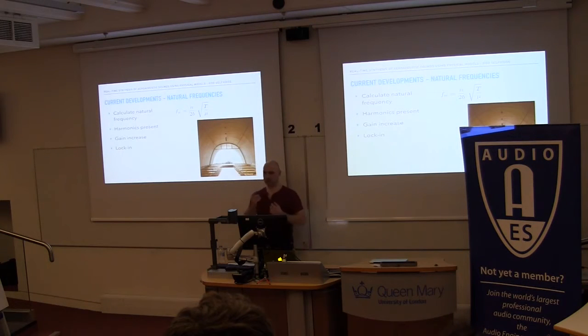And what also happens is the wind speed might go up a bit, but the mechanical process says, no, you're still going to shed at my speed. So it creates a kind of lock-in, and so the tones actually stay at set tones. It's not as relevant at higher modes, in the lower harmonics like the 1st, 3rd, 8th harmonics. By the time I get to the 80th harmonic, it's a much more damped effect.